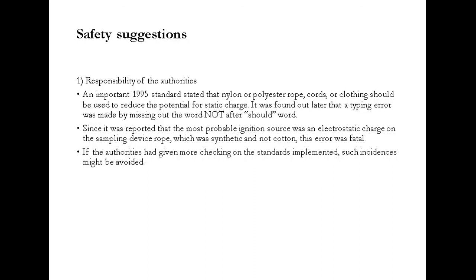During the investigation after the event, it was found out that an important 1995 standard stated that nylon or polyester rope should be used to reduce the potential for static charge. It was found out later that a typing error was made by missing out the word "not" after the word "should". Since it was reported that the most probable ignition source was an electrostatic charge on the sampling device rope, which was synthetic and not cotton, this error was fatal. If the authorities had given more checking on the standards implemented, such incidents might be avoided.